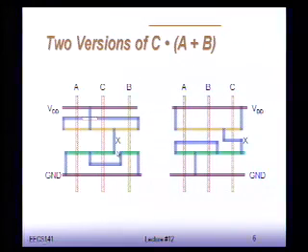But now look at what happens. The drain of C has to be tied to the output, and if the next one over is B, if I basically make a multi-finger device out of these two, I get that the output is shorted to the drain of B, which is not what I want, right? I will implement a different logic function.